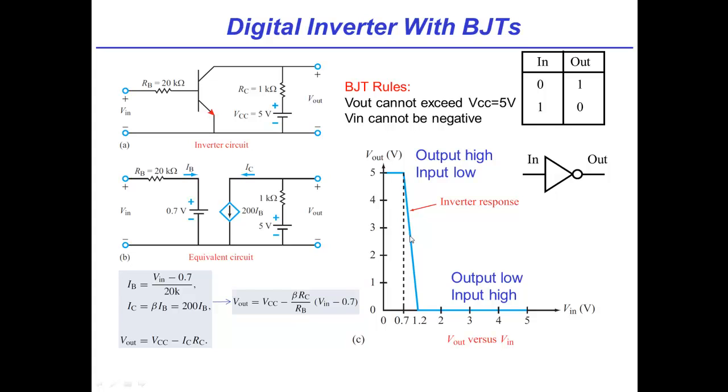Okay. So the last take-home message I've got is that the BJT is kind of a current amplifier, and we can use it that way, or we can set it up in a circuit that allows us to translate that current amplification into a voltage amplification. That's right. And we've done that here by putting in a resistor, which basically converts an input voltage into an input current. That's pretty cool.